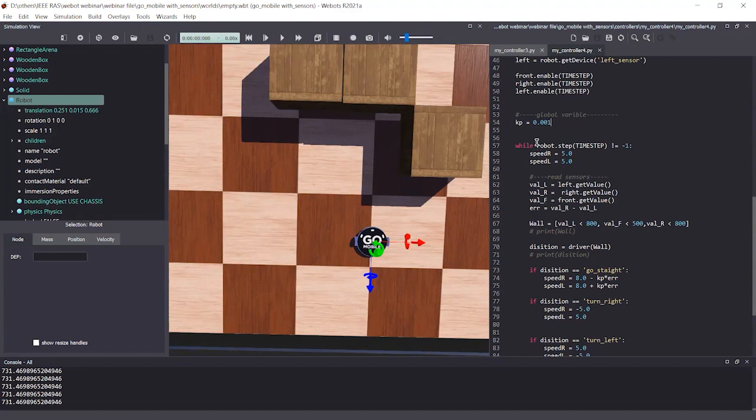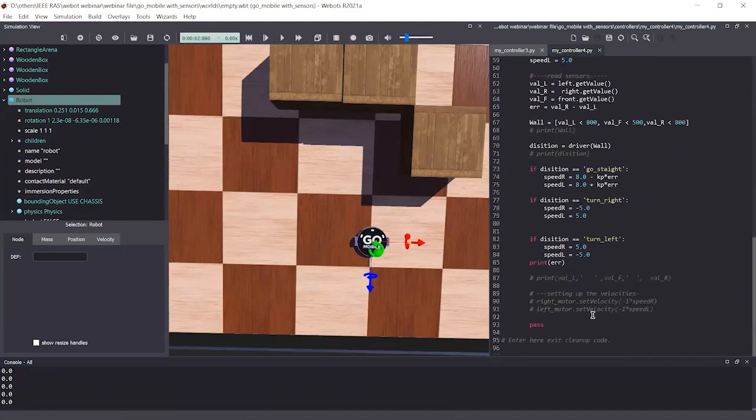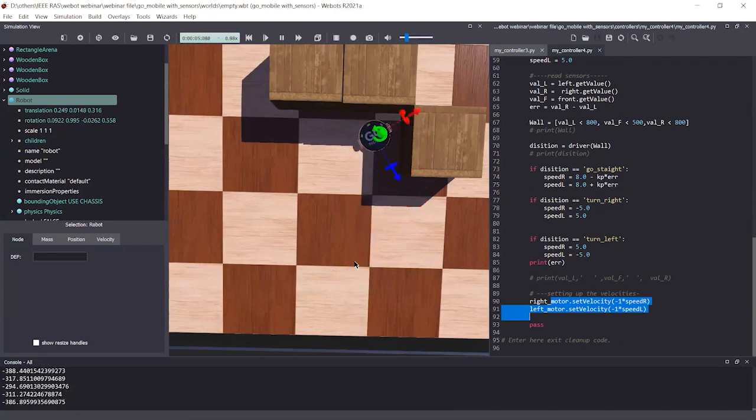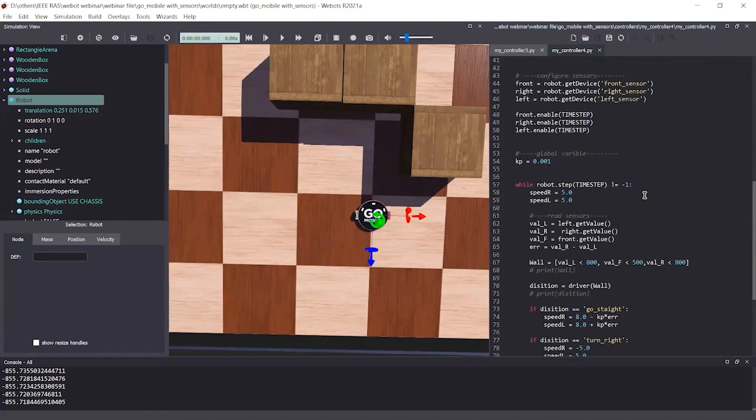Tuning means giving the right values to this constant in order to perform correctly. So let's see. We need to uncomment this speed, right? Okay, now the robot is going forward, and okay, still not great. So I'm going to move toward this side because it's taking time. And I'm going to increase this value to 3. Let's see whether 3 will do it. Okay, now it's going.